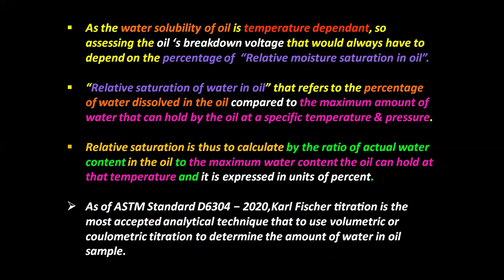As the water solubility of oil is temperature dependent, assessing the oil's breakdown voltage would always depend on the percentage of relative moisture saturation in oil.